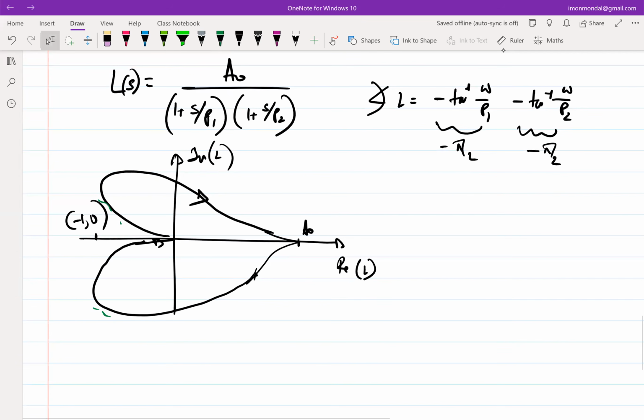So now we need to have a measure of how close we are to instability, because we saw that in case of zeta equal to 0 or zeta less than 1, you had ringing, which means it's quite possible the system will take forever to settle if you give it a step input, which probably will not be acceptable in most applications, right? So it's not only sufficient to say now that we are stable or not, right? We need to see whether you have sufficient margins from stability, right? It's like whether I am at the edge of the cliff or I am slightly away, right? So I'll have to be more careful if I am at the edge of the cliff, or at least I need to know how close to the edge of the cliff I am.